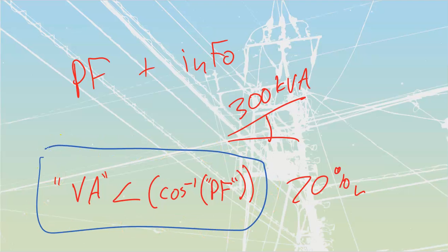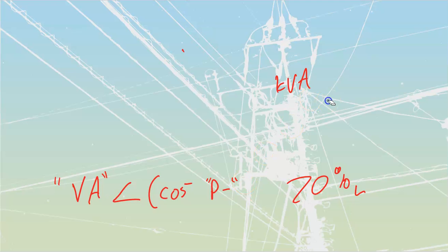Let us get to what we need to understand, the power factor correction, relatively quickly. The next example that they gave you was where they took two values. They said, look, we've got a load that's got 750 kVA and 400 kilowatts, and I want to know what I have for my actual power factor.